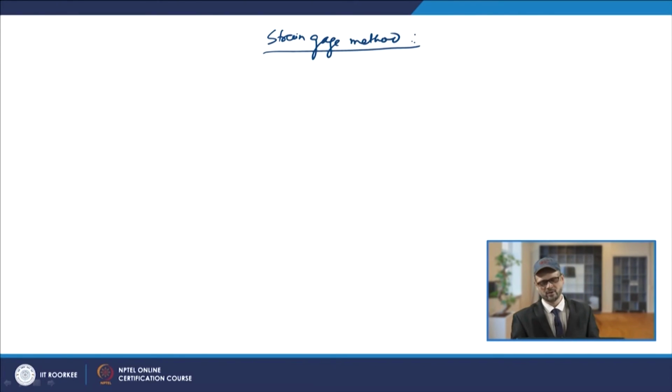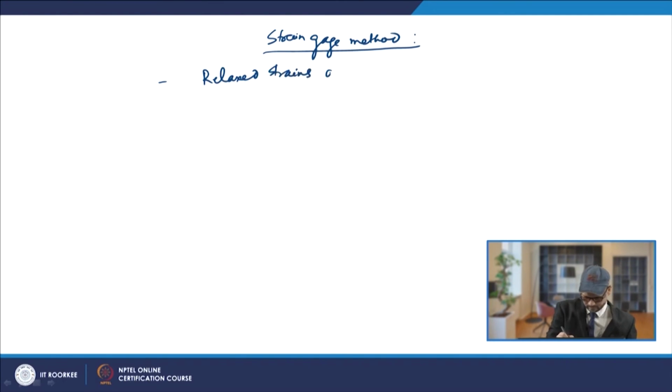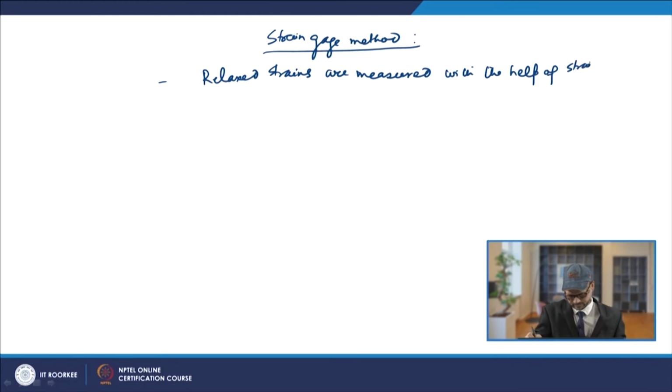You will have strain rosettes here, and you will have automatic measurement of the strains, and based on that you can measure these stress values. So the relaxed strains are measured with the help of strain gauges.